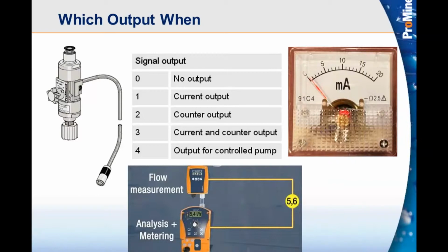It's a powered loop that we're sending out. They do not have to series power onto that loop. In fact, if they series power onto that loop, they're going to burn that output circuit. So don't do that. But we can have that remote display as well as the local display right on front of the door.